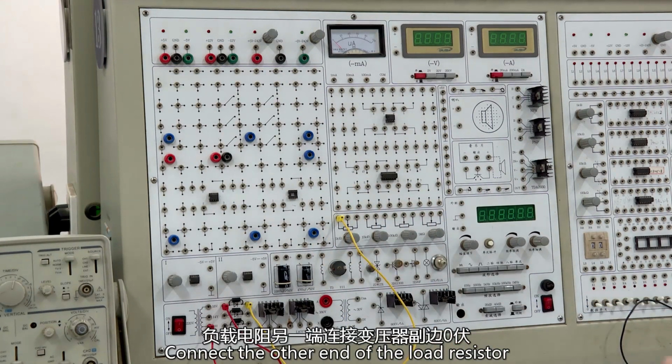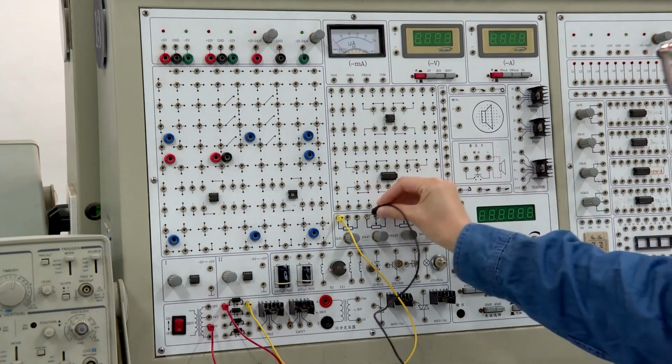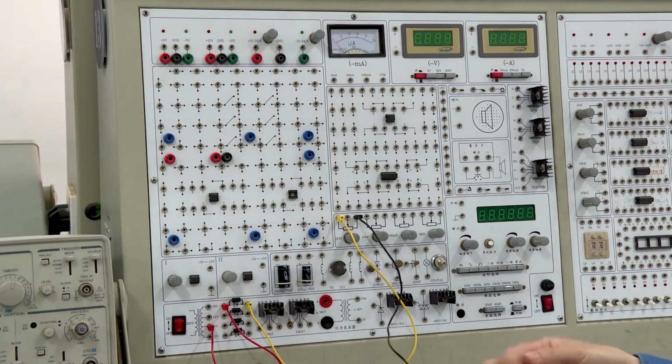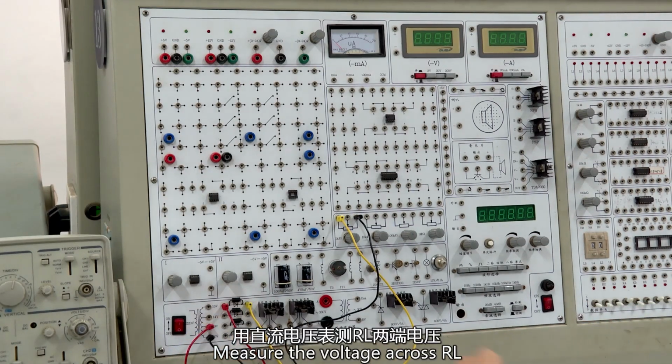Connect the other end of the load resistor to the 0 volt on the secondary side of the transformer. Measure the voltage across RL with a direct current voltmeter.